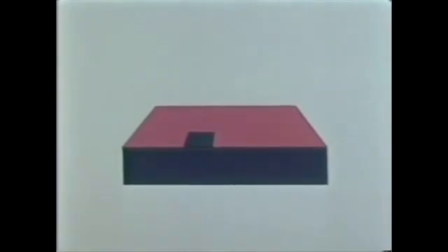The wafer is then exposed to acid. Those areas of the passivating layer not protected by the hardened resin are etched away. In the next operation, called diffusion, the wafer is exposed to a dopant. This impurity diffuses through the window and into the silicon below, forming the collector of a transistor in our integrated circuit. But notice, at the same time diffusion is taking place, more oxide is being formed. This is the essence of the planar process.